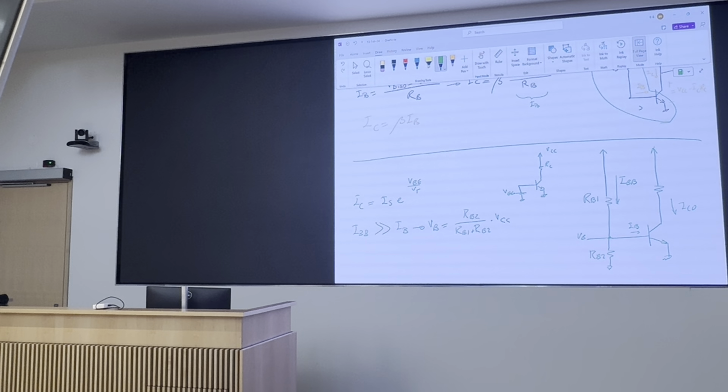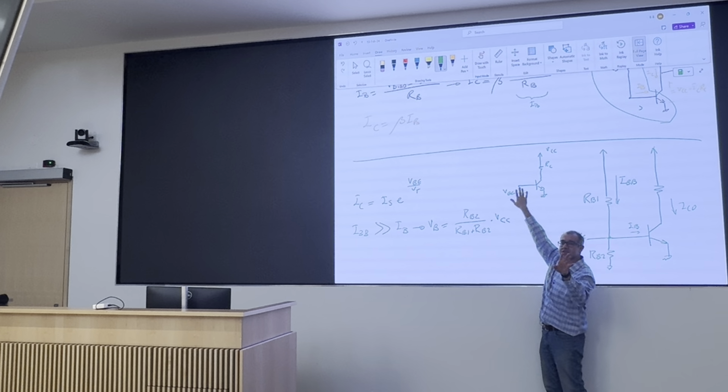I can check the notes. Yeah, the turn-on voltage of the diode drops by about 2 millivolts. Right? So it's 2 millivolts per degree centigrade. It's actually reliable enough that you can make a temperature sensor. Same thing happens here. You have a diode, 2 millivolts per degree centigrade. So you make this circuit, you do all your calculations, you know you need 0.72 volts to bias this device where you want.